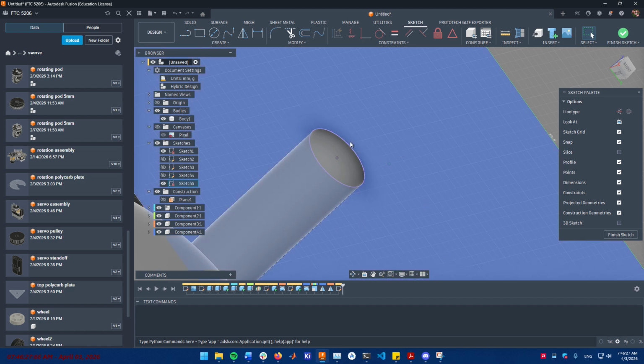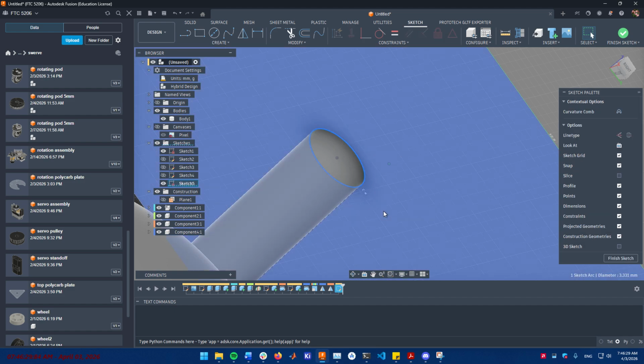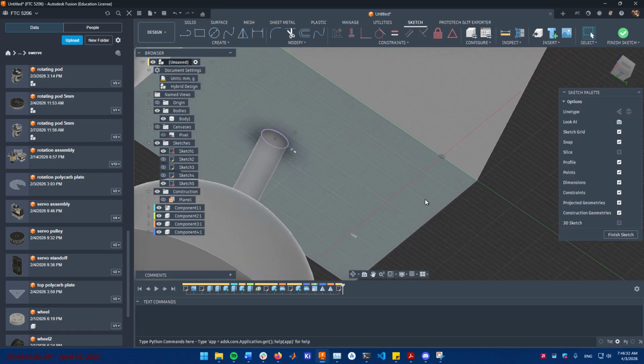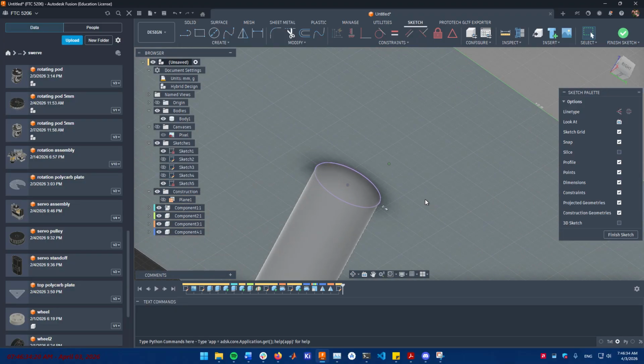And now we have the leg geometry here, but if we create the hole right now, that also won't be fabricatable, because as you know, doing 3D printing, the holes get smaller and the outside geometry gets bigger just because of heat expansion.